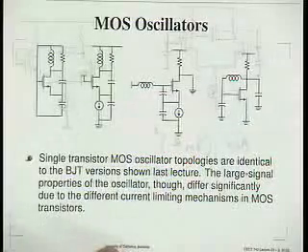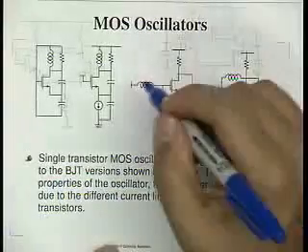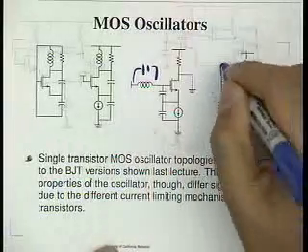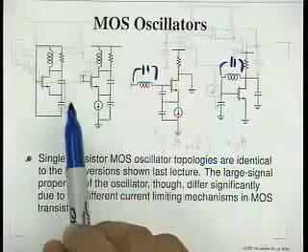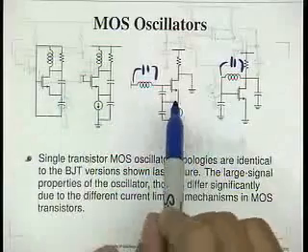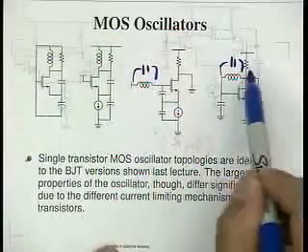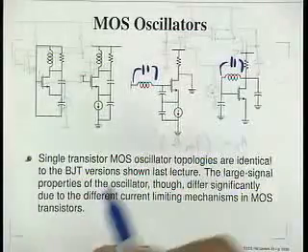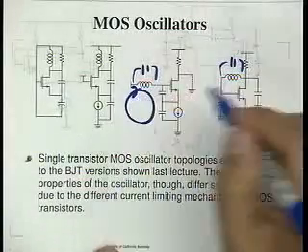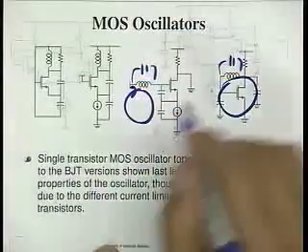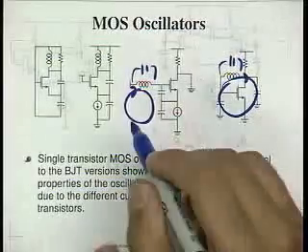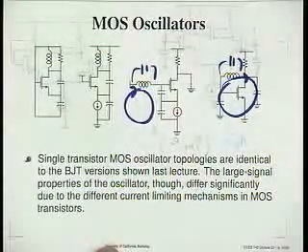And we also talked about last lecture that technically these oscillators have caps in shunt here, if we just go directly from here to here. But there's no need to have this extra capacitor. We can actually eliminate it and form resonant tanks as follows. So this is the resonant tank here. This is the resonant tank here.